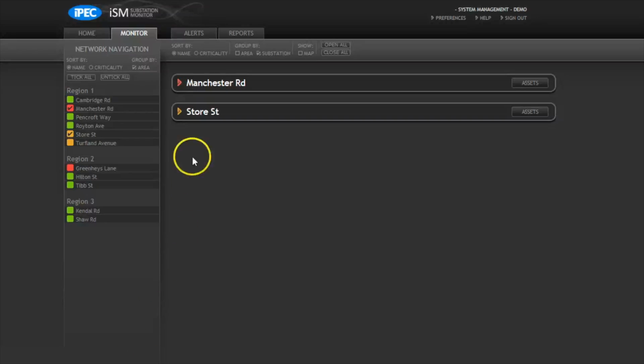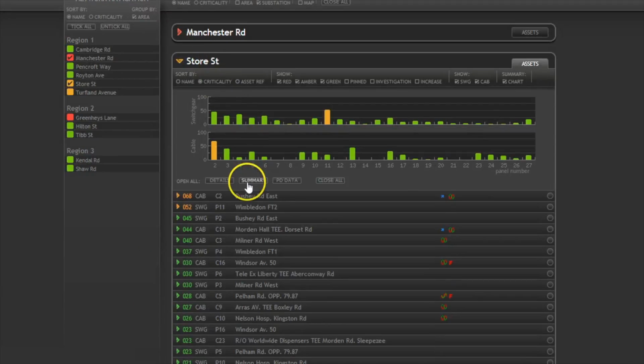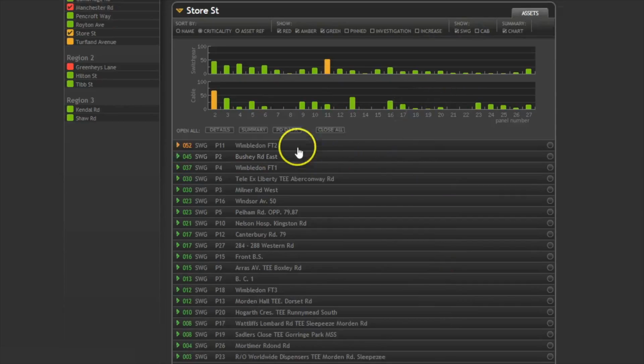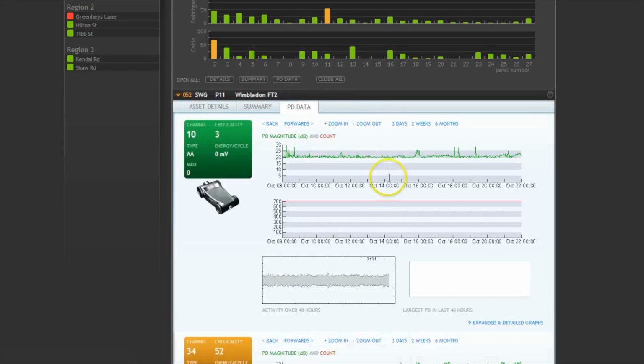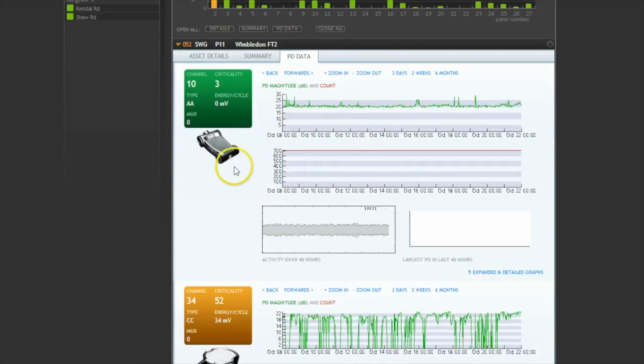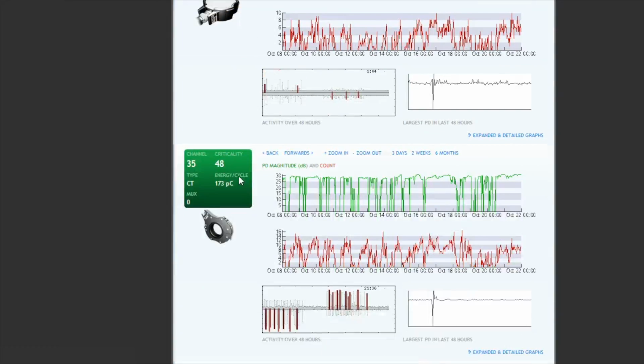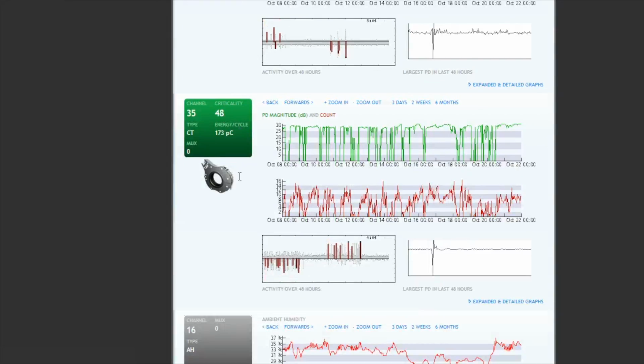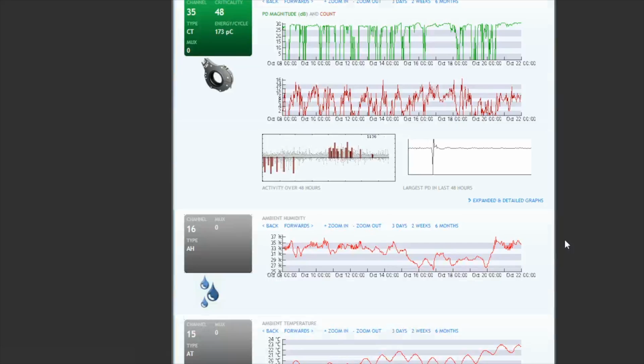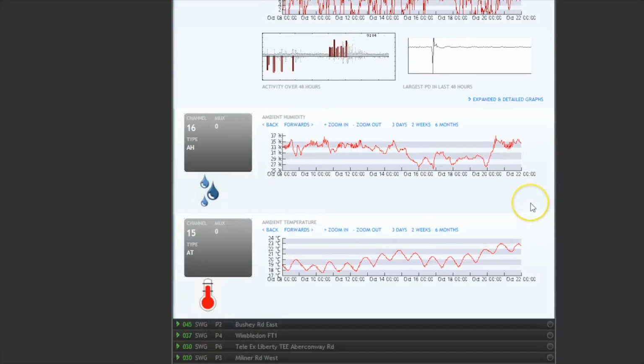At this substation, there is high switchgear PD activity. There are actually 3 PD sensors in this case that are all sensitive to local discharge of different kinds. The ultrasonic acoustic sensor, the TEV capacitive sensor, and the HFCT, which detects PD from both cables and switchgear. With switchgear assets, the system also shows temperature and humidity, as these can influence discharge in switchgear.